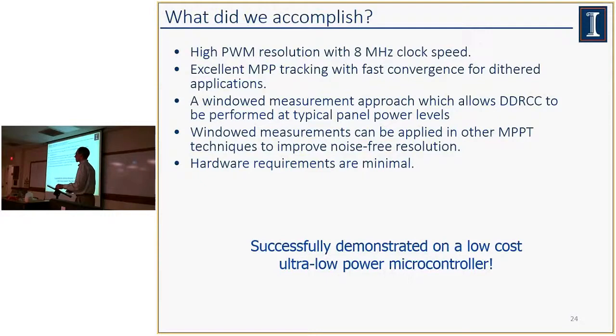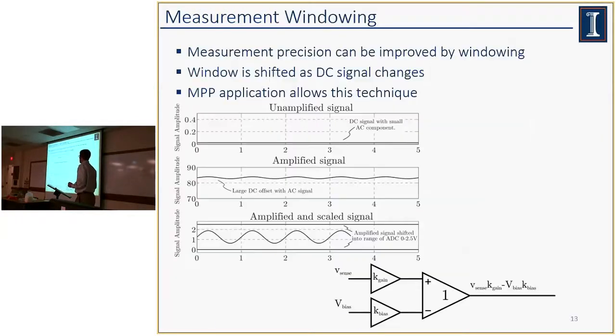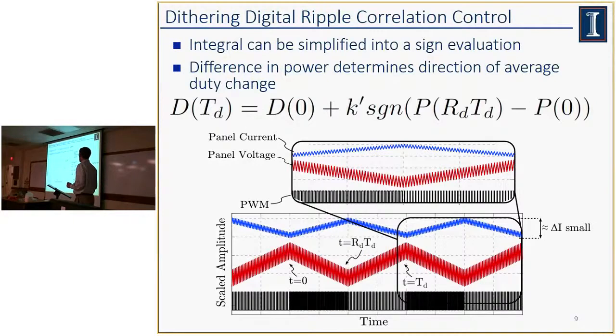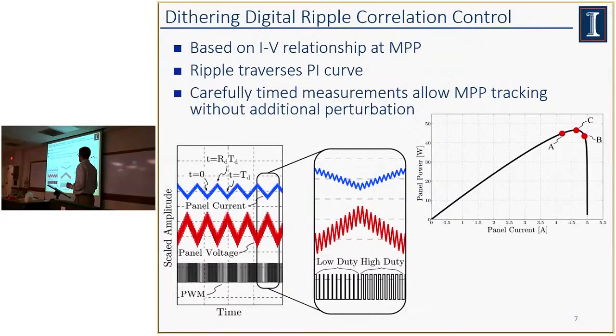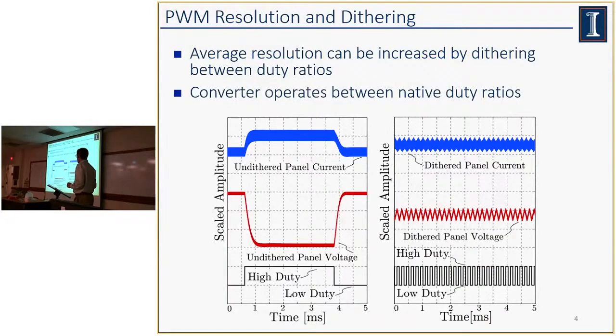Maybe I did not get you before, but when you talked about synthesizing a certain duty ratio, you talked about a high and a low initial part of the synthesis. So how are these decided? What do you mean by high and what is meant by low? How to define the high and the low duty ratio? These are adjacent native duty ratios. So this is 1/32 and 2/32 in this instance. Those are the closest we can get using the native PWM hardware.